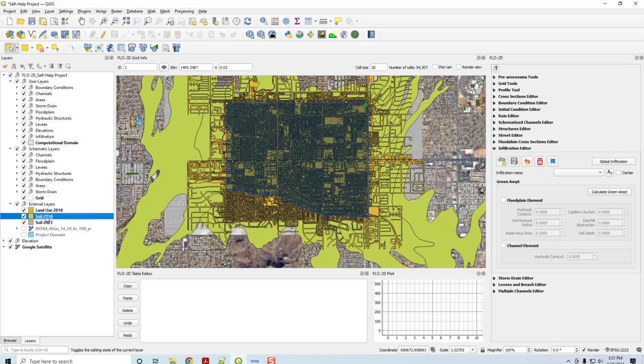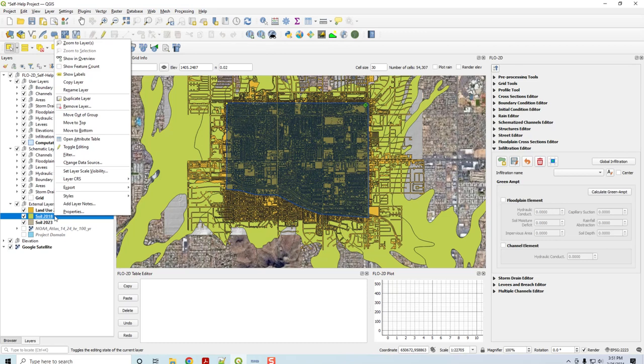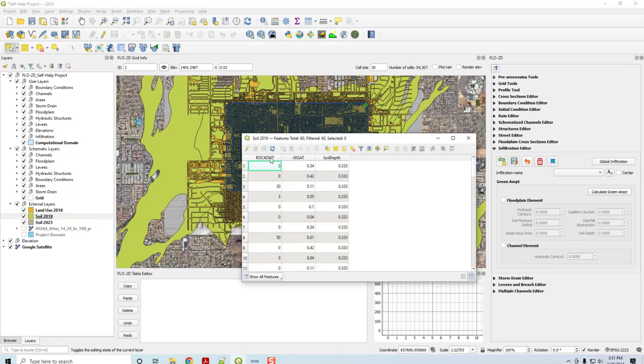This is the 2018 Flood Control District method. So in Maricopa County, this was the method they used as of last year and previous years. This has an impervious related to rock outcrop, so that's your soil impervious. And this is your XKSAT, the hydraulic conductivity, the average hydraulic conductivity of your soil layers.